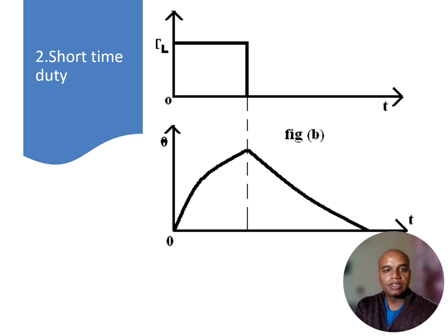Applications like compressors and conveyors run on the continuous duty cycle with constant torque requirement. The other duty cycle is the short time duty cycle. Here we can see that the load runs for a certain or very short period of time, and then it remains off. The motor temperature reaches a certain value while the load is on or running.